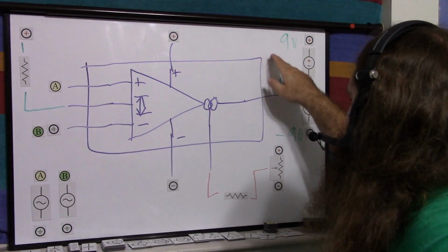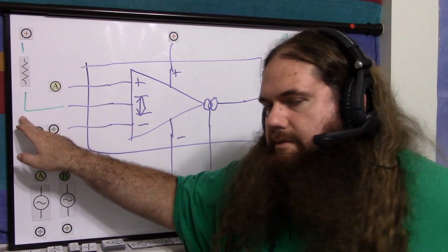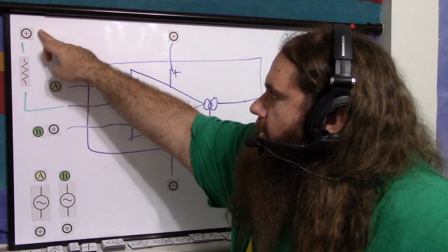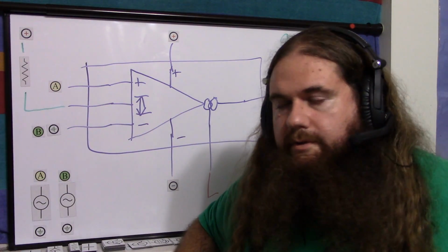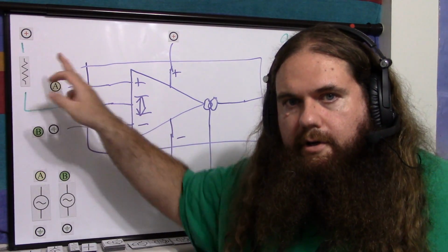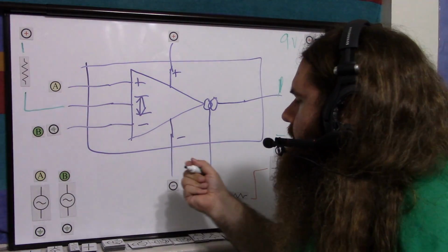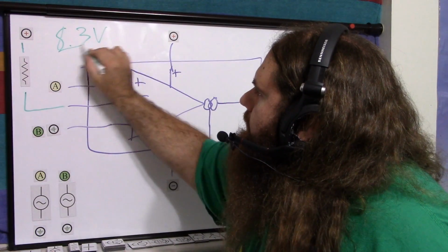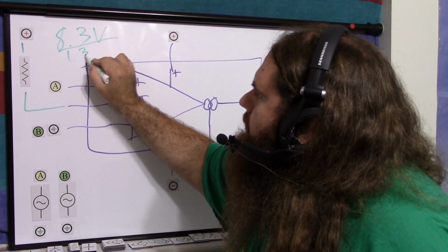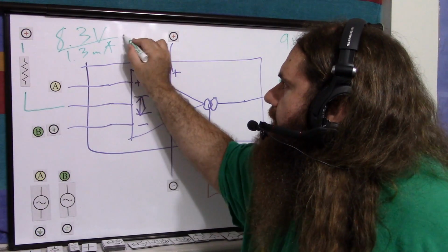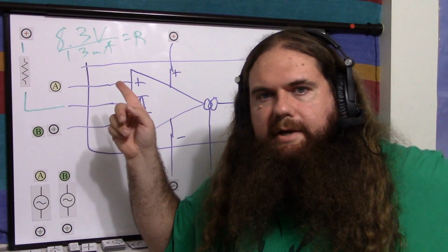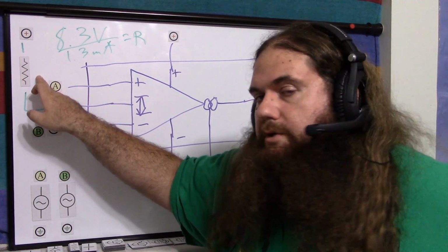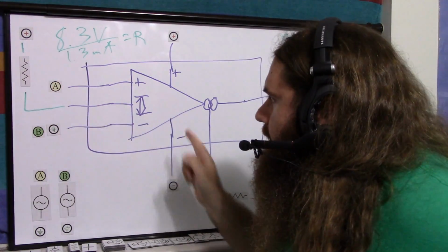So just hook it up this way, and it says a diode drop above 0, so about 0.7 volts. So positive minus 0.7 is the voltage, and then you have your current. So let's say you want 9 volts, so let's say that's 8.3 volts divided by, let's say 1.3 milliamps, and once again, that's your resistor. The absolute maximum rating is 2 milliamps, so 1.3 isn't going to hurt it. So you just decide on your resistor value, hook it up, and leave it alone.